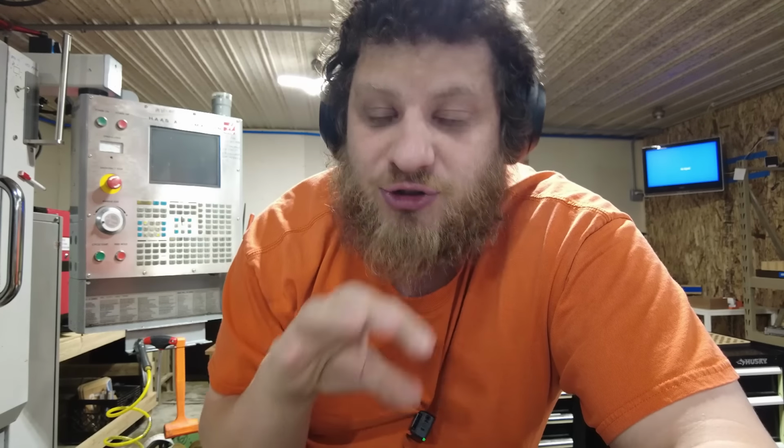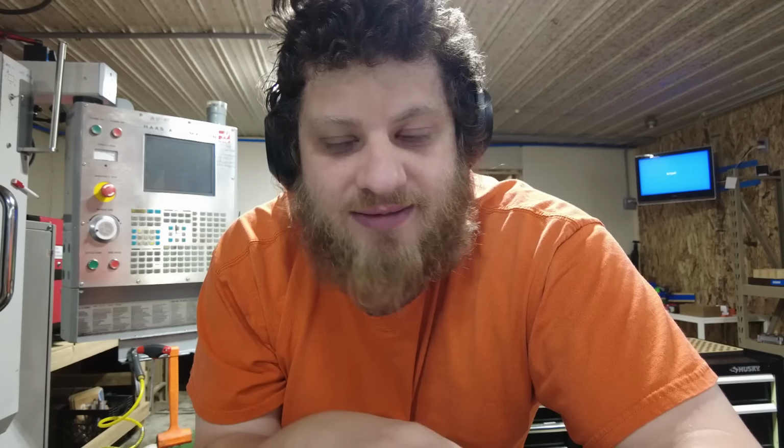Let me do a better job of explaining this container component. By having a top-level container that you put your actual machine part inside as a subcomponent, you keep Fusion from getting confused by swapping around the models. If you didn't have that top-level container, when you replace the model, Fusion would get confused about where to generate the stock and where your work coordinate system is and what actual model you're machining.